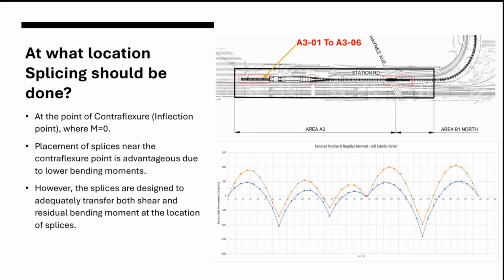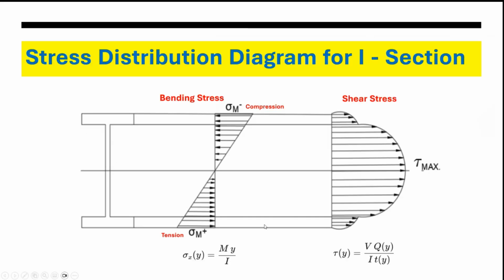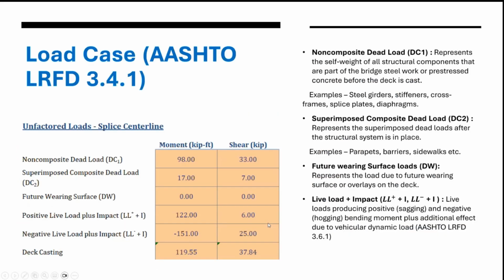Yeah, for the splice plates, we look at the locations where we put these splice plates. We take into consideration what the shear stresses and the moments are at that particular location. So we design it for that moment and the shear stresses. As we can see, these are the different moments and shears we have taken into consideration.